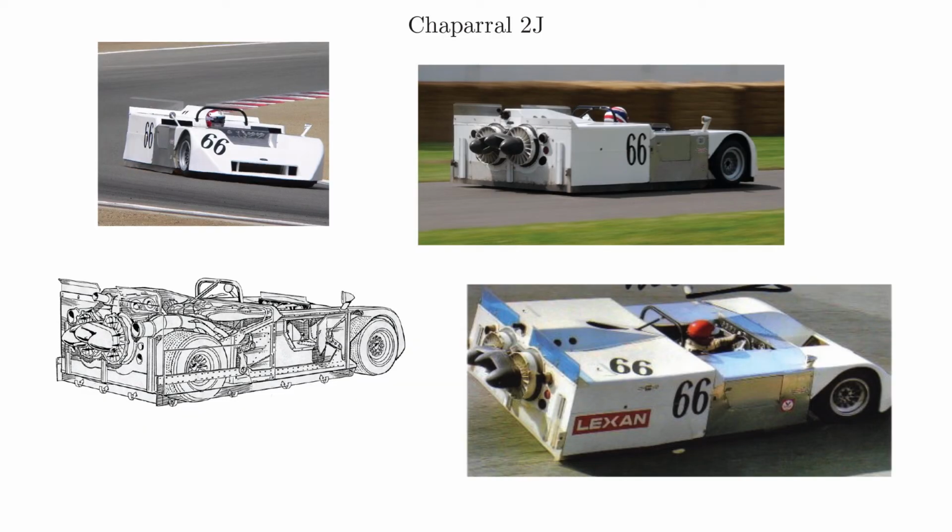So the way he did it was very clever. He managed to make a skirt out of Lexan, okay? So he actually puts these two fans on the back, as we can see in the picture here, and they're powered by a snowmobile engine, actually. And so he actually just sucks all the air out of this, and because it's skirted, he creates a low pressure zone that pulls the vehicle down against the road.